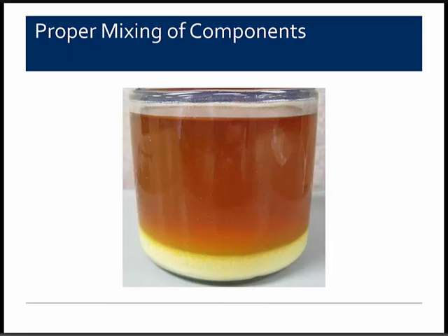The solvent acts as a carrier to deliver the binder product, and during this process, when the material is installed, this solvent is what flashes off or evaporates and leaves behind the adhesive product, which forms the bond between the two products you're making.